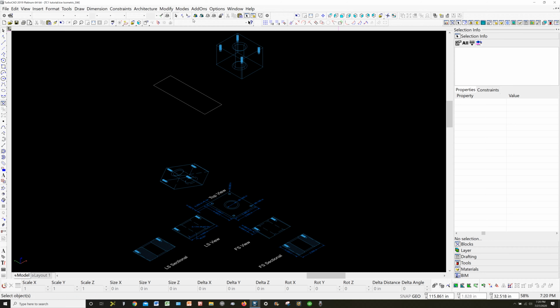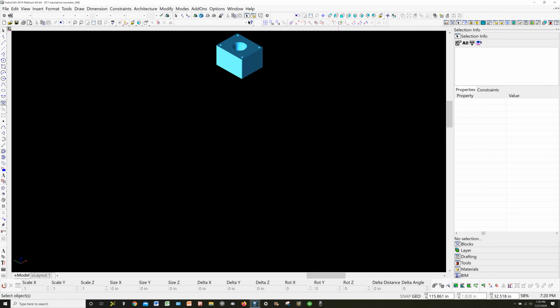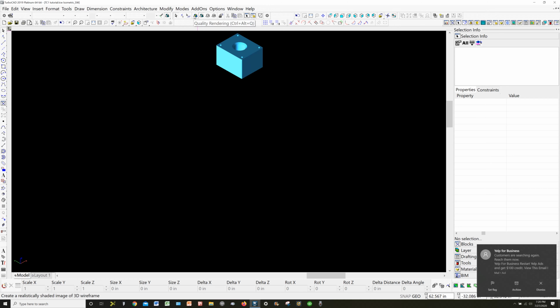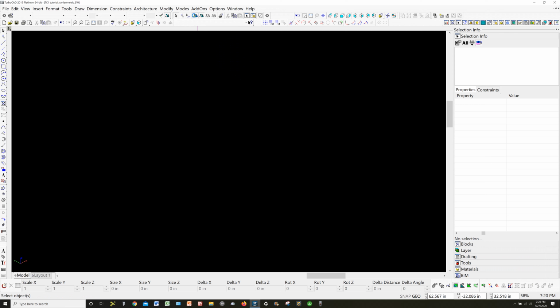Over here, I have my rendering styles. Okay, these guys right here. This guy here should give me draft rendering. And I've got it set up where all 2D stuff disappears in render because I don't really need to look at it. And then this is the photorealistic rendering, which you only use when you need it because it really slows stuff down. It makes it hard to even drag the item around so you can look at it. Right now I'm trying to drag it. They're not letting me. Okay, but if I come down here to draft,